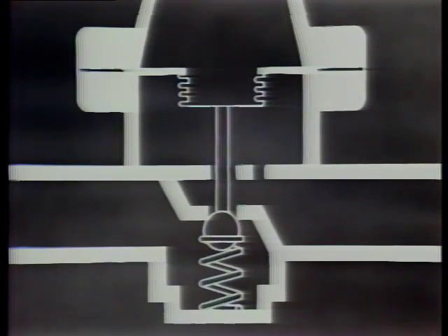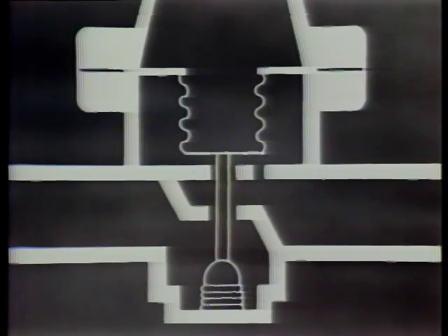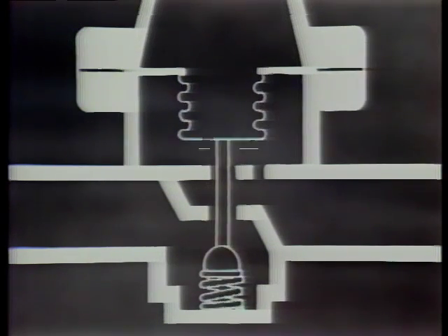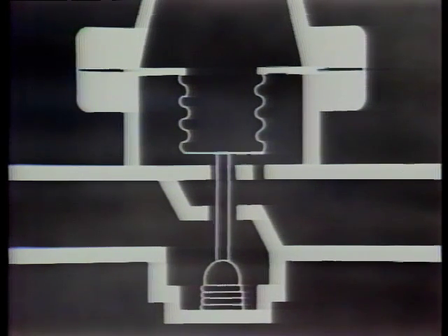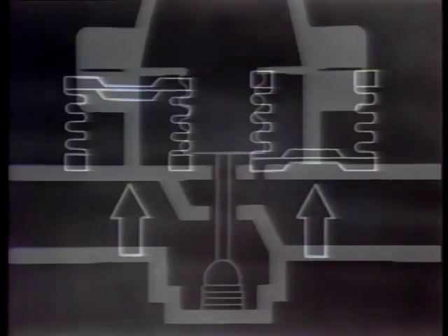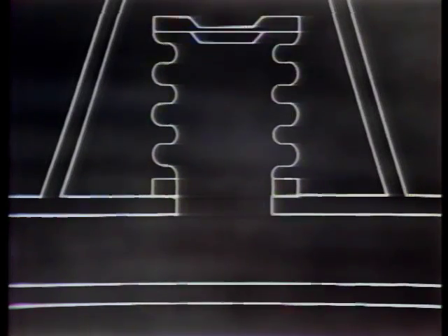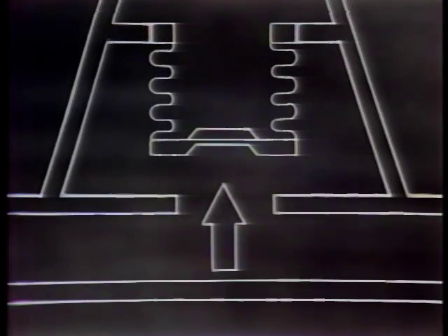Next, we have the already familiar bellows. As a controller, bellows offer longer valve travel and greater flexibility than the flat diaphragm. Bellows are also limited in pressure handling, but are stronger than the diaphragm. The bellows can be mounted in the body so that the pressure is either internal or external. A bellows with the pressure on the inside is more likely to burst in high pressure. A bellows with high pressure on the outside may have the convolutions crushed, making it inoperative, but it will not burst and pressure integrity will be maintained.